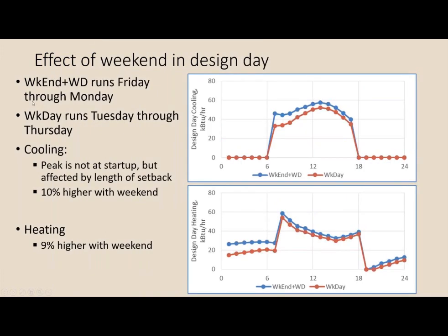So a couple more examples of things that I tested. I put these examples together based on a couple of years I spent using the program, the design sizing features, and different problems I ran into, explaining them to help you avoid those pitfalls that I hit. So this is a case where you're including the weekend or not including the weekend in the design day period.